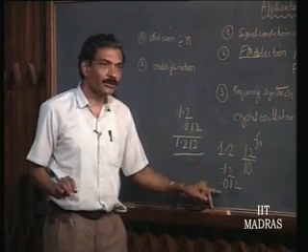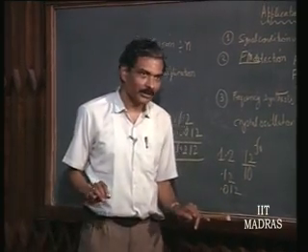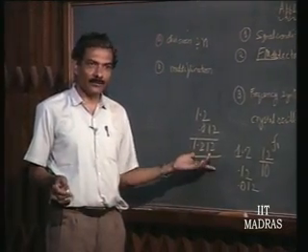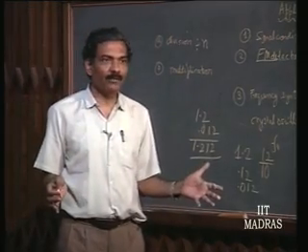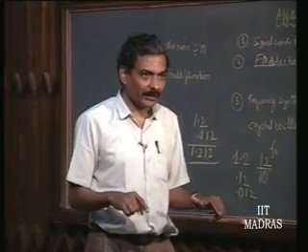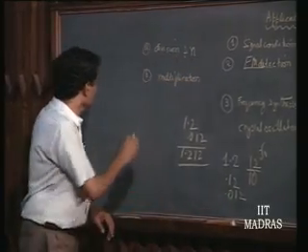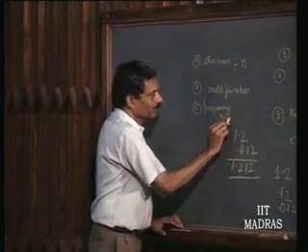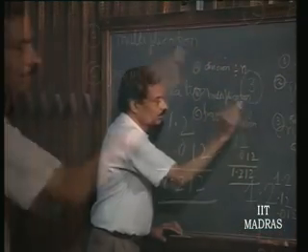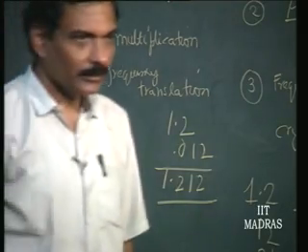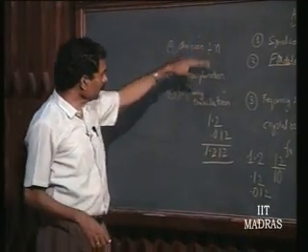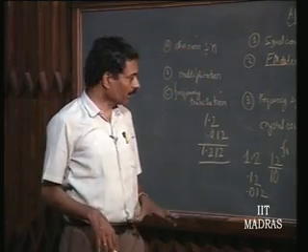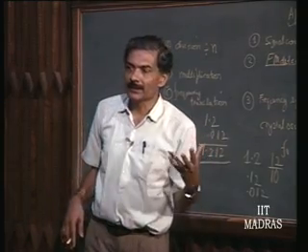Then I go on using decade counters alone, and obtain all this, and therefore, now I can get any frequency to any accuracy by using this technique of what? Addition or subtraction, that is called frequency what? Translation. Okay. So, if you couple on to this scheme of multiplication and division the frequency translation scheme, then it becomes a very powerful frequency synthesis procedure.